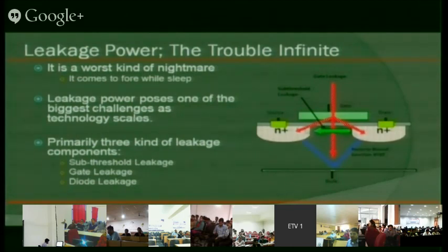There are gate leakages from source to gate, drain to gate, and from gate to body. So all these currents will flow. This current through the gate flows because the gate oxide is also shrinking. This is because of tunneling. Though it's an oxide, certain electrons can tunnel through the oxide. So there is a current here.